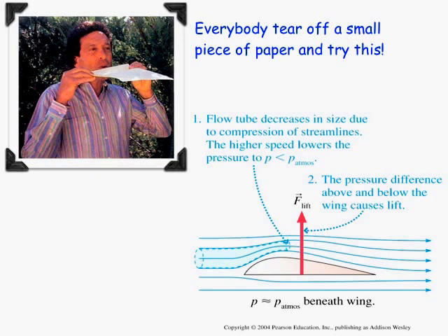So if the air is flowing faster up top, the kinetic energy of the air, the fluid, at the top of the paper is greater as it's being blown across. If it's greater kinetic energy, some other form of energy must have dropped. In that case, greater kinetic energy density corresponds to lower pressure. So the pressure is lower up top of the paper, and the paper gets lifted up from the higher pressure below. This is the concept behind the lift of an airplane wing.